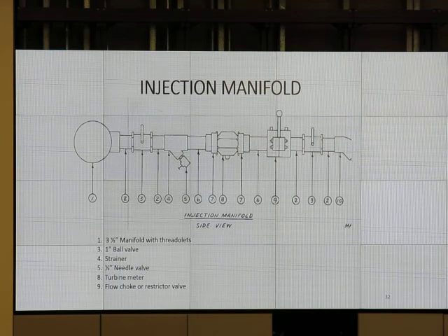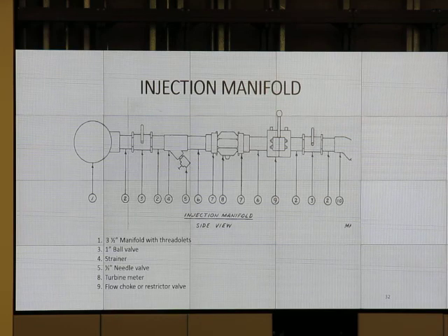So everybody has reasons for doing things the way they do. But if I had a choice, I would control from a single point on my header, put all my meters there, all my control valves, and then just send the water to the wells, rather than going to the well and adjusting. You wouldn't do both. That would be a duplicate redundancy.